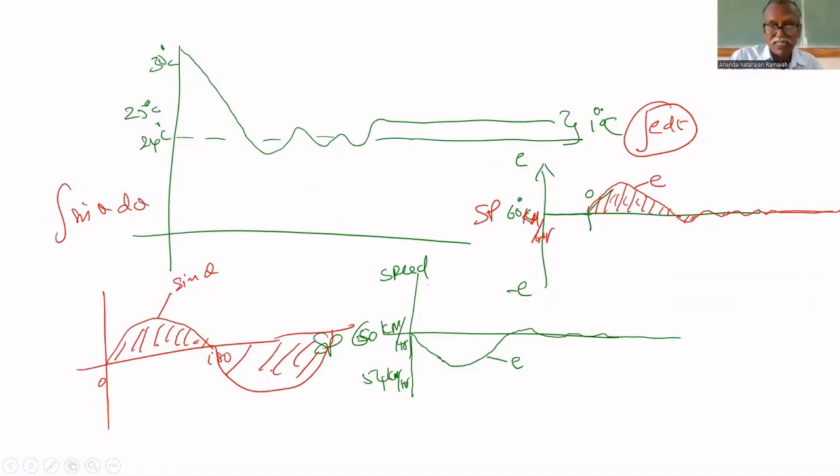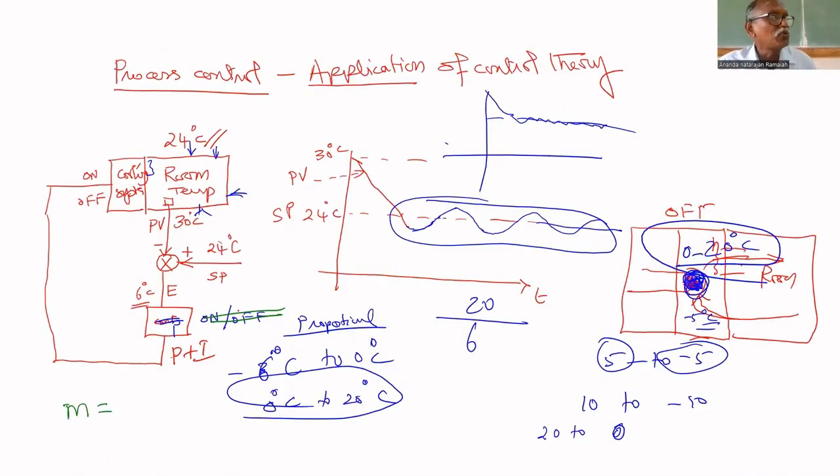That's all about PI. The D mode is there, which we rarely use. In your experiment, you won't use it. Anyhow, I'll tell you about one more mode, that's why it is called a PID controller. D mode is to speed up the response. D mode means derivative. This is the integral mode, I. Integral of E dt gives the area under the error graph.